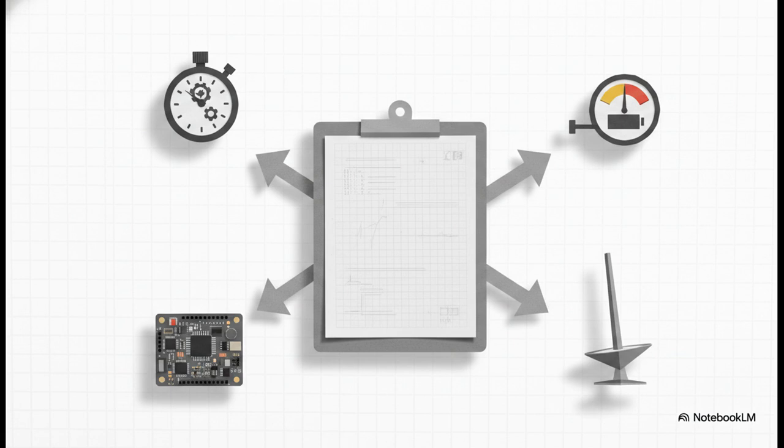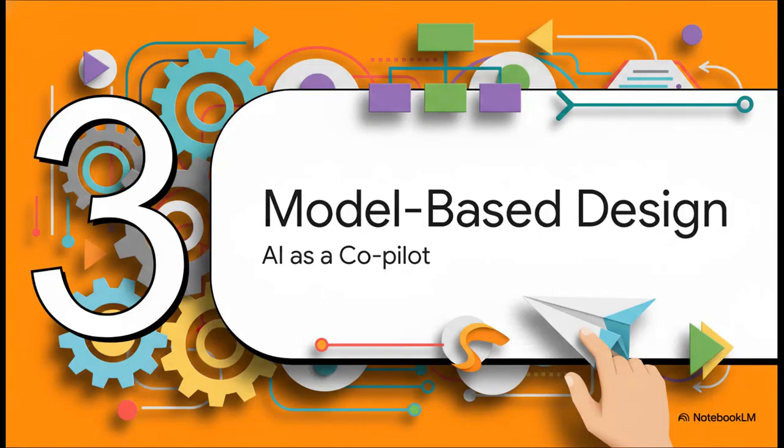Think about it. How quickly should the pendulum spin up? How fast must it settle? How much wobble are we physically allowed to tolerate? We're setting strict limits here. For example, we absolutely cannot exceed motor commands over 12 volts, or we're going to fry the servo. And practically speaking, the code itself has to actually fit and run reliably on a Raspberry Pi. So we feed these overarching goals to our AI agent and have an iterative back and forth to get these parameters crystal clear.